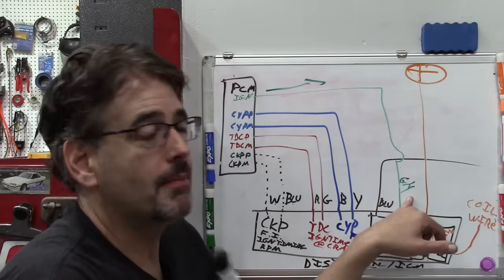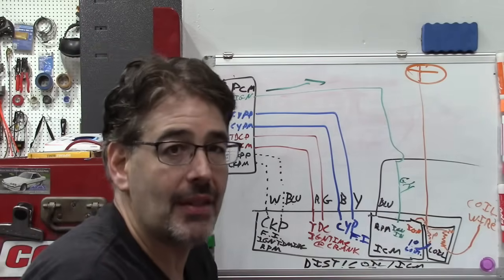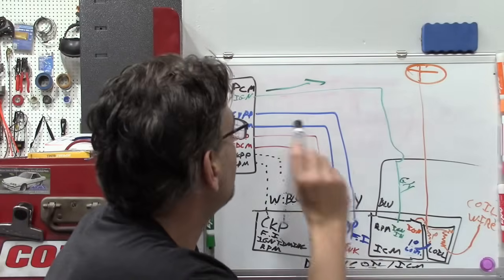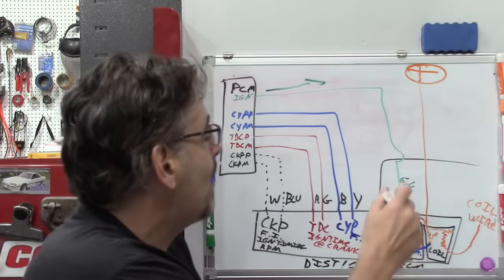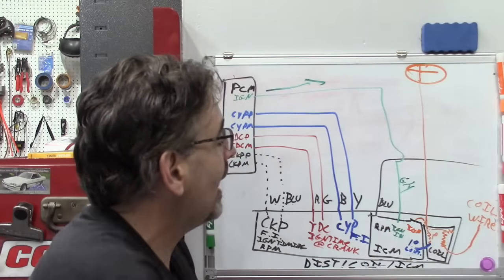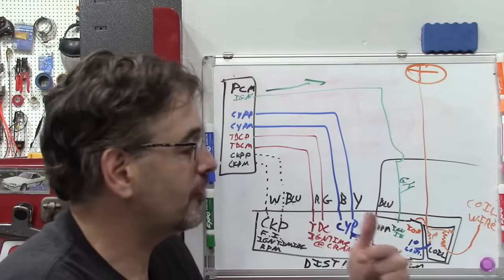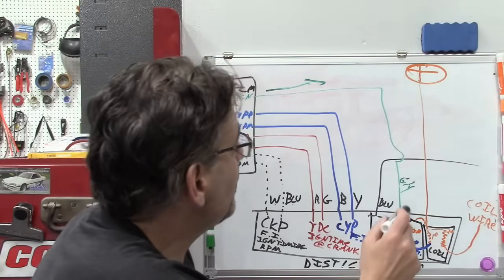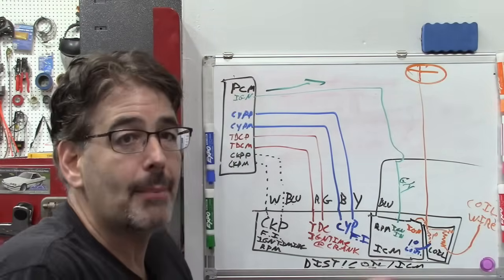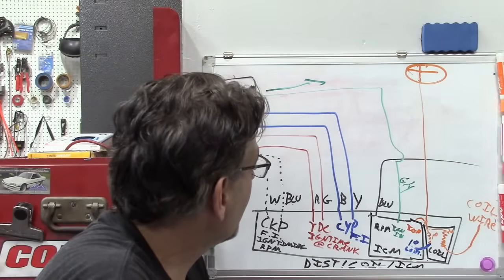Now that's a little bit more challenging done than said, and that is because usually this is really low amperage here, so it's not like I can just back probe this and put my test light there and see it flash like with the injector signal, the fuel injector signal. These generally don't work like that where there's not that much amperage in doing this.